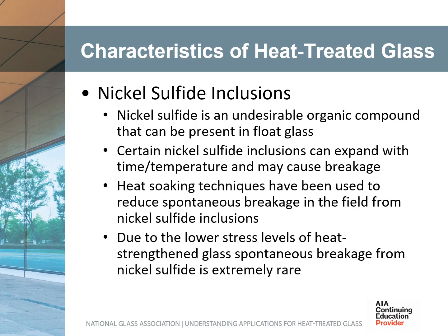In annealed glass, these are harmless and are considered on the same basis as all other inclusions. However, during the processing of fully tempered glass, the nickel sulfide inclusions are transformed into a state wherein they will expand irreversibly with time and temperature. If the inclusion is tightly held in the glass and not otherwise surrounded by a bubble, the expansion may produce enough stress to cause spontaneous glass breakage at a later point in time. The fracture caused by the expansion of the inclusion is quickly propagated in fully tempered glass because of the high tensile stresses inherent in the thickness in the center of the glass.